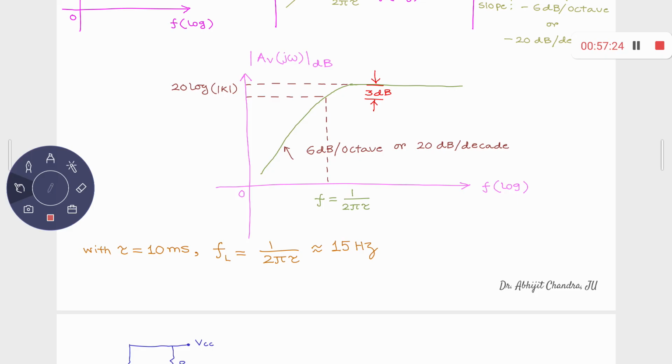So you cannot make it so it is in the range of... It is 1 micro, no? With one micro, I've got this. With 1 microfarad. Right. Now, if you can make it say in the range of picofarad, then what happens? If I select the CC value in the range of picofarad or nanofarad, what happens? In that time, your time constant will be less, so FH will be or FL will be increased. That you don't want.